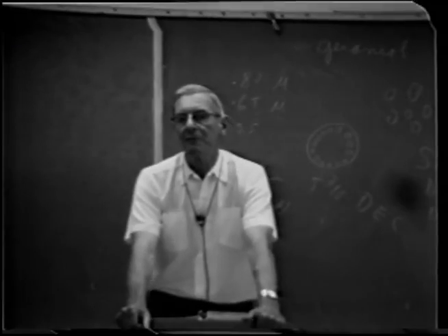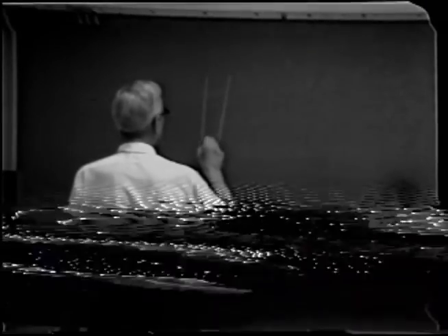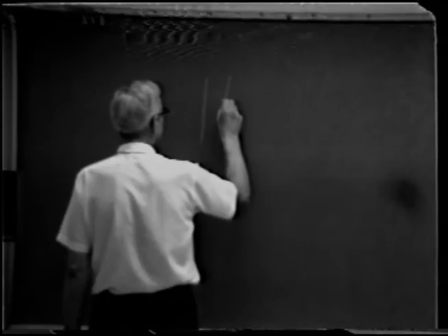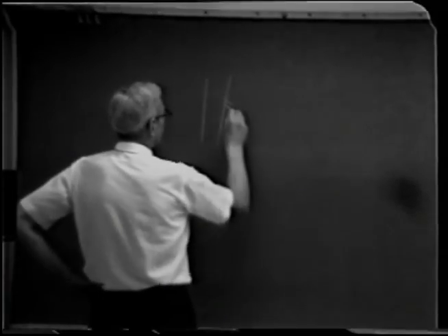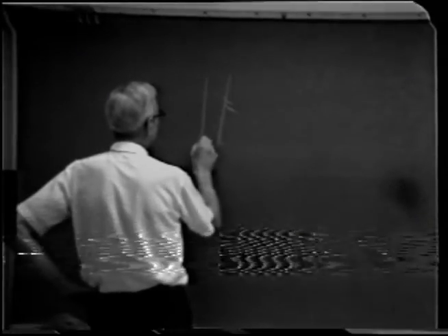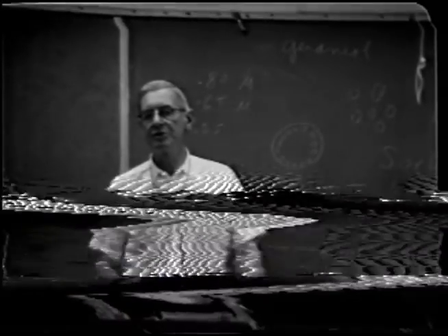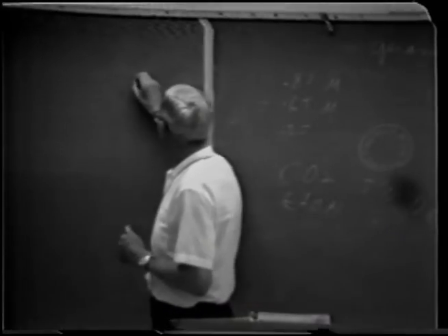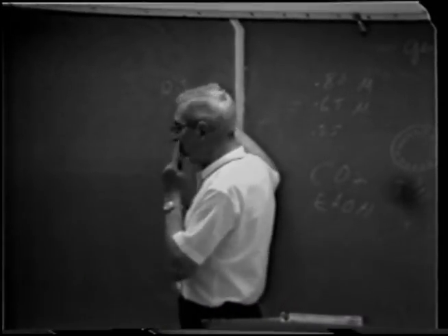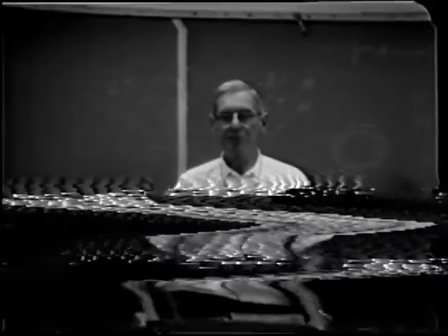A number of years ago, bottom filling spouts were developed. You know, the ordinary filler fills practically from the top. They developed spouts that fill actually from the bottom. And tests showed that if you use a bottom filling spout, you reduce the amount of oxygen introduced into the wine by up to as much as 0.5 of a cc per liter, which was appreciable.